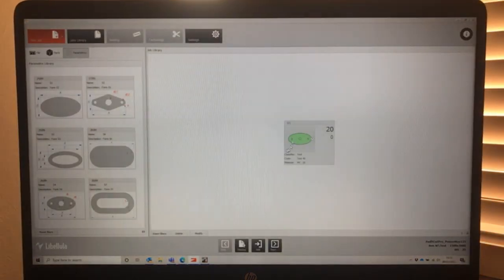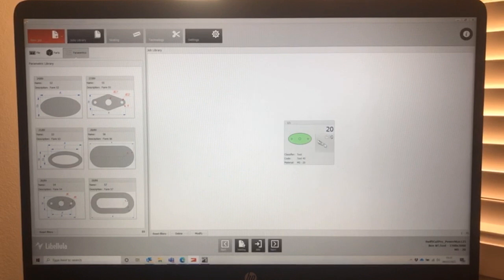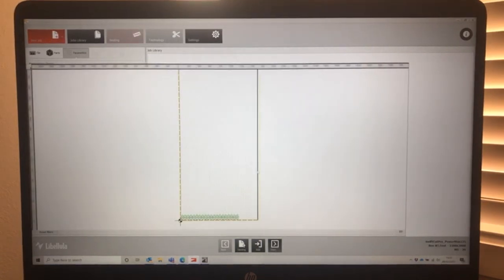Click OK, and now on this right hand section it's loaded the part in as we've put it in with all the details for a quantity of 20. At this point you can load other components in, other items, other parametrics or DXFs to build up the job of what you need based on the material thickness that you're working to. Once you've loaded them all in, select next.